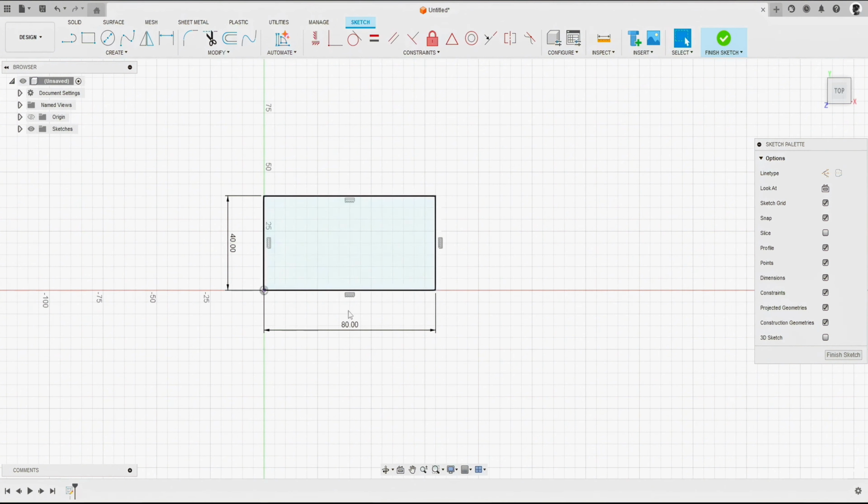A rectangle that features all black lines, that's fully constrained. Now you notice these symbols that will pop up here. Now these indicate constraints, which we'll be covering in a later lecture, but just to give you a bit of a heads up, this symbol here represents a horizontal constraint. Now this symbol is tied to this line. So this line is indefinitely horizontal, but we cannot change the angle, cannot make it vertical, or that is horizontal, and likewise the same with this one. So that's one of the powerful features behind using the 2-point rectangle tool.